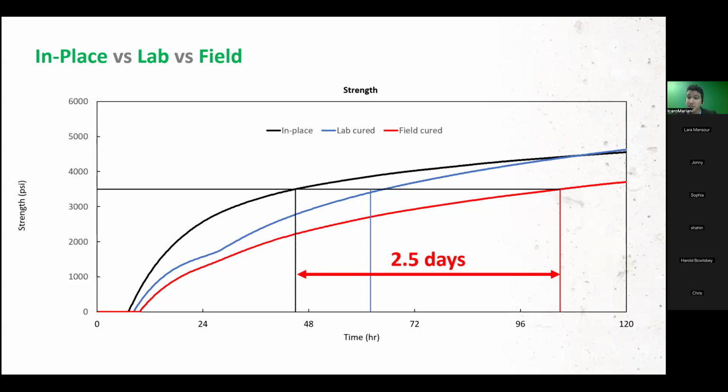100%, because ASTM C1074 is the standard. So if you're outside a DOT project, let's say it's just a high rise, and you are in the United States, yes, it is accepted. That's great. It's just the DOT acceptance, because they follow AASHTO standards, right? So that's why it's a little bit different, but the concept is the same. So 47 states accept the maturity method for DOT projects. Got it. And MTO as well here in Canada. Our difference is that it's not provincial, it's federal, but we follow ASTM as well.